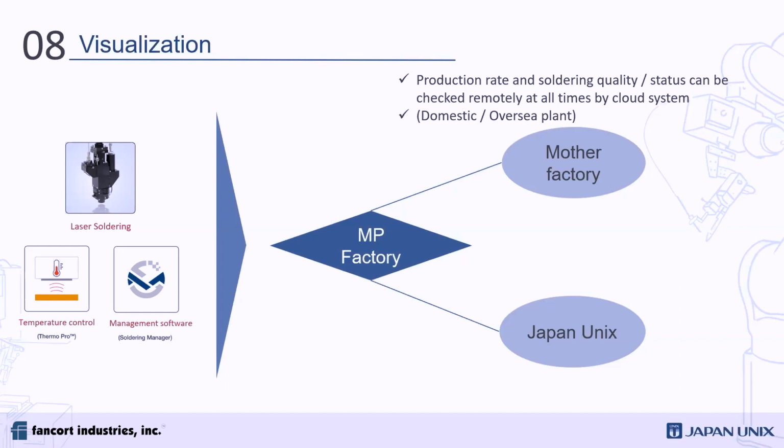The Soldering Manager and the pyrometer combination is also able to track each of your production pieces. So you may want to scan the barcode or QR code or whatever, to track the loading in your station. And then our soldering performance, all the temperature data, soldering recipes, all kinds of data are able to be attached, and then you can upload to your MES.